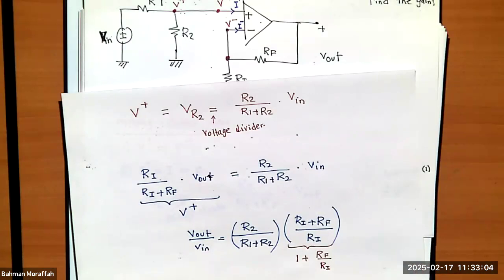So let's just have a quick recap of what we're doing whenever we have a circuit with an op-amp in it, or more than one op-amp in it. As soon as we identify that the op-amp is an ideal op-amp, we know the golden rules hold. The rest is just choosing a method that we like. I use a lot of current divider and voltage divider. You don't have to. You can do KVL, KCL, Norton analysis, mesh analysis, whatever method you like.